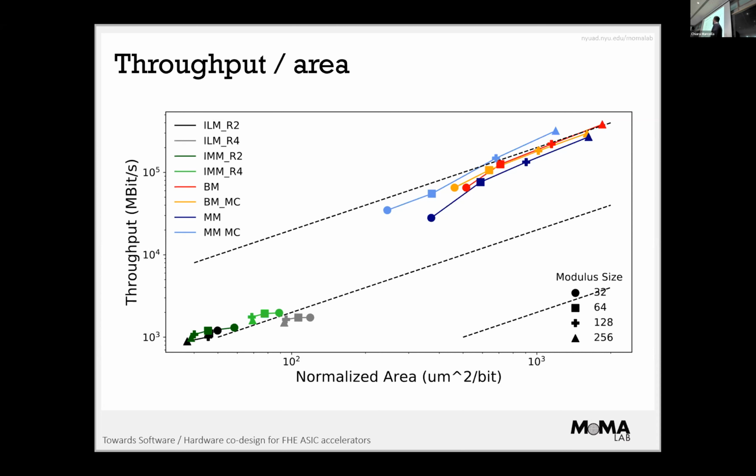So the pipeline is relevant. Another point is that all these designs have an initiation interval of 1, so they can take one operand in every cycle. That makes a more fair comparison between the algorithms. We want them to be fed one operand per cycle because we hope the multipliers won't be the bottleneck. However, what seems to be the bottleneck is that data doesn't arrive in one cycle. It needs more. That we're still exploring.